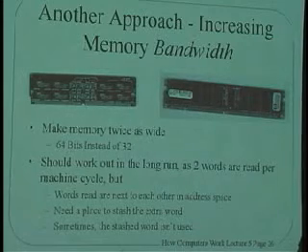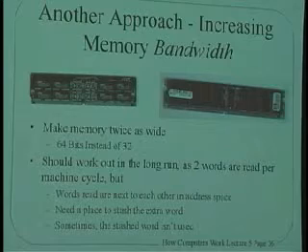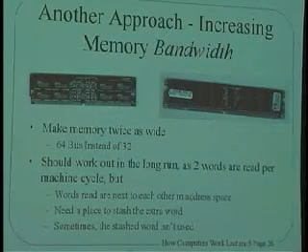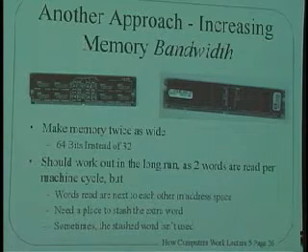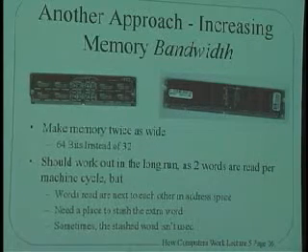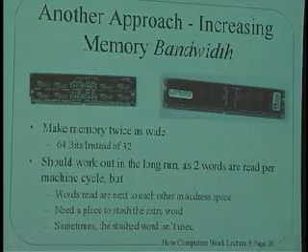How to make memory faster? The simple thing is to make the memory really wide. Use wider words. So even if you have a 32-bit machine, if you have a memory that is 64 bits wide, every time you do an execution to fetch some stuff from the memory system, you get more bits, and then those are good for 2 cycles as opposed to 1.